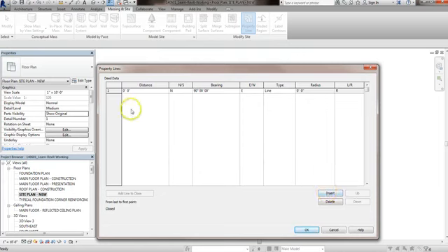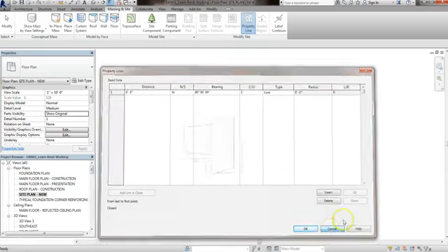And for your last one, it normally doesn't work. If you type in perfectly what the engineers give you, that last line almost never connects. We've probably done dozens and dozens of houses, and for that last line, we always just click add line to close, rather than typing it in. And then normally it comes out pretty good. But we're not going to do that now.